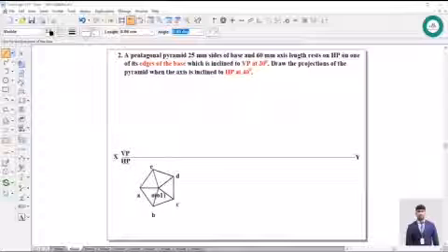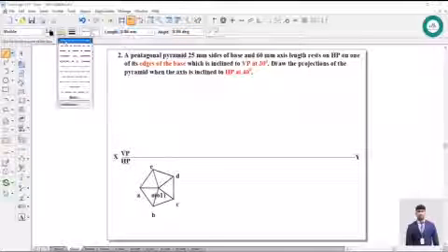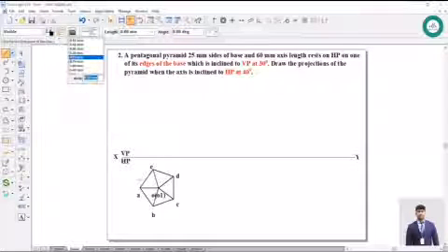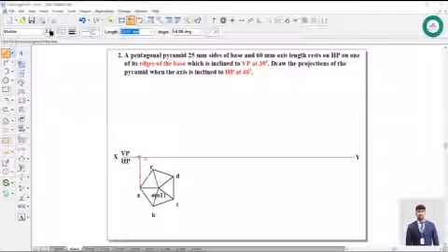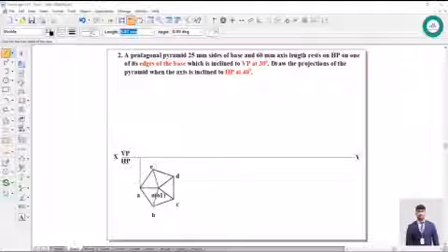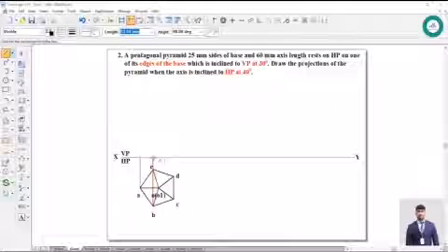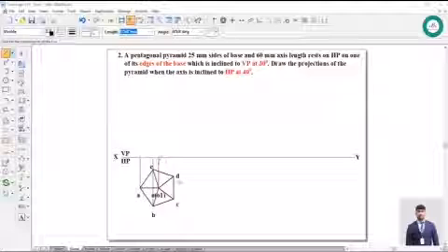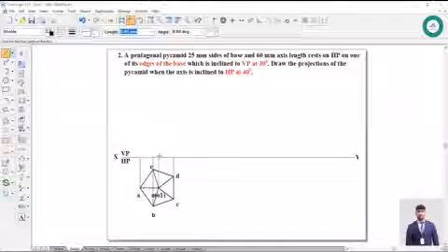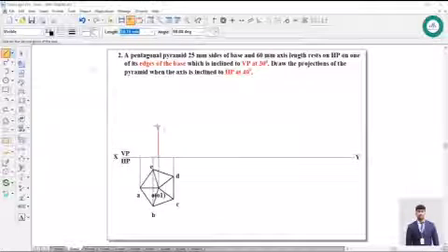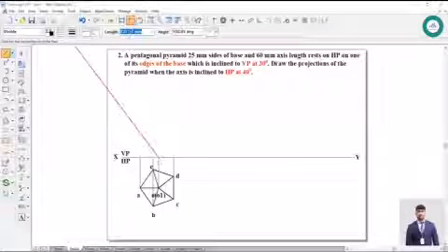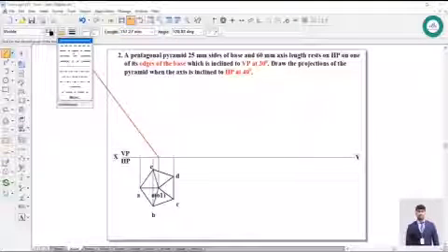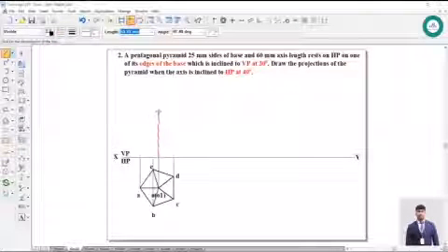Next, after this, go to the line command, take the suitable type as well as width, project this to XY line. So that is from A and from B and E and from the center also. So after projecting this, ensure you always raise the height of an axis from the center itself. Click here, take the suitable line, raise this for a given height, that is 60 mm.